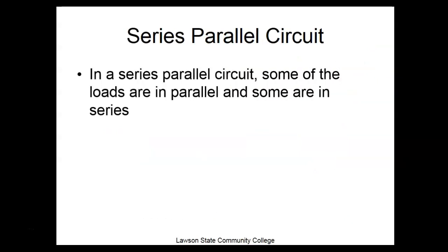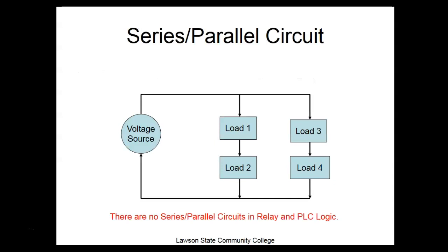Series parallel, this is the way electronics are wired. This is the way most Christmas lights are wired, in series parallel. So what happens is you'll lose a light and just a section will go out. That's the sections that are in series, but another light section will stay on. Used to, Christmas lights were totally series, and you'd have the whole string go out, and you'd go find a good bulb, and you'd go all the way down through the thing, replacing the bulb to see when it came on.